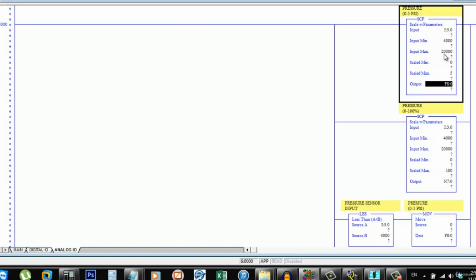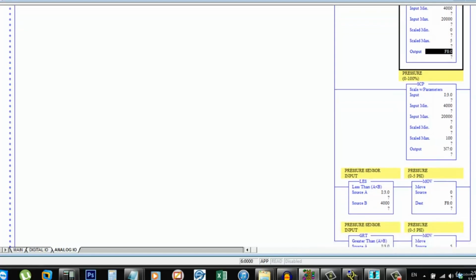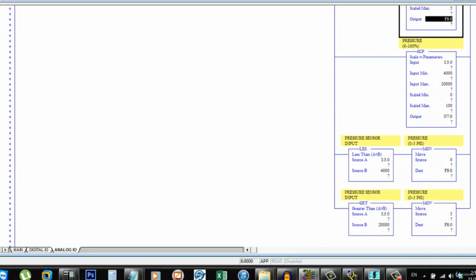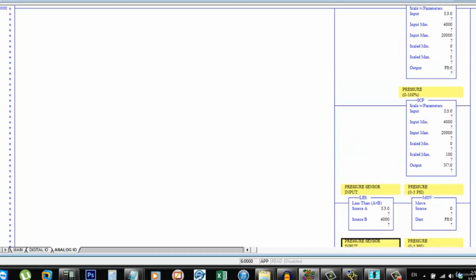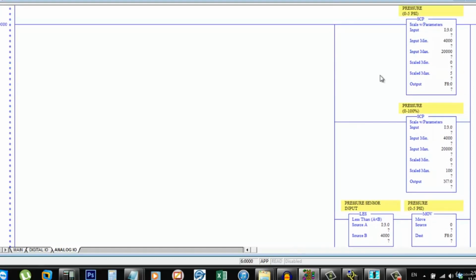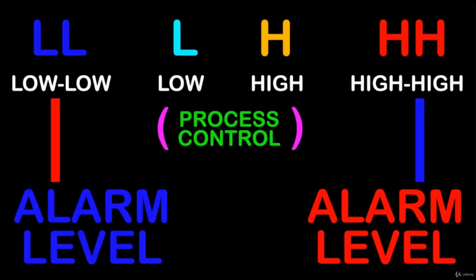And assuming that this float is sensitive to out-of-range conditions which could upset math down the road or displays down the road, we've also put in some conditional programming to handle low signals and to handle high signals. So that is just a little bit of the potential complexity of handling analog inputs.